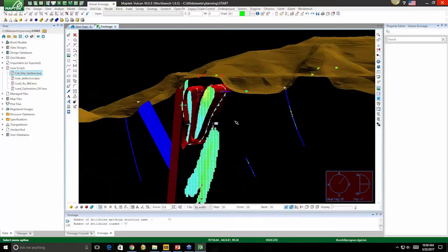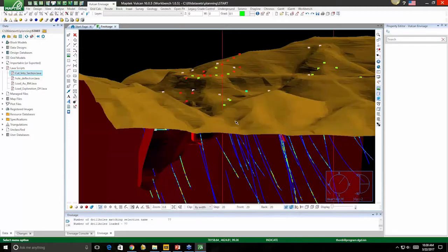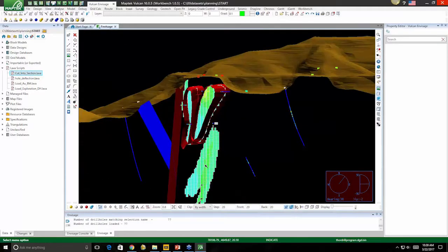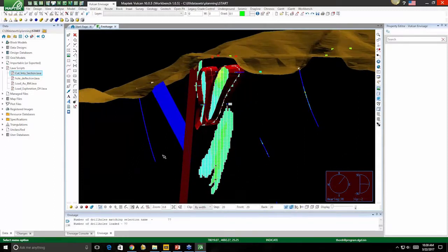So if I were to set my view back into the plan view and then press 1, it navigates me back to that view. So that's really helpful because you can see where this might be a potential target. I want to cut through these areas. I don't have any drill holes that pierce this specific orientation, so maybe these faults are actually bringing in some more gold that I'm just not aware of. So let's get digitizing in 3D.